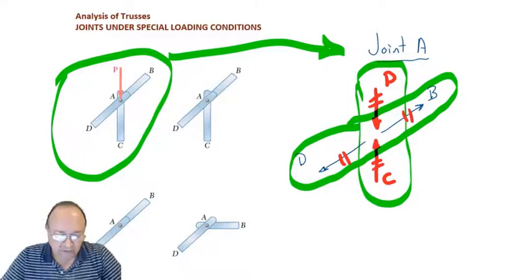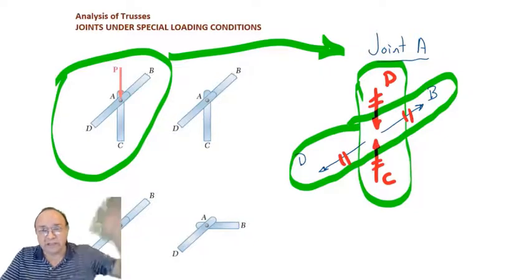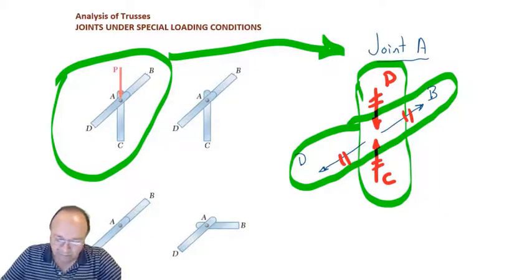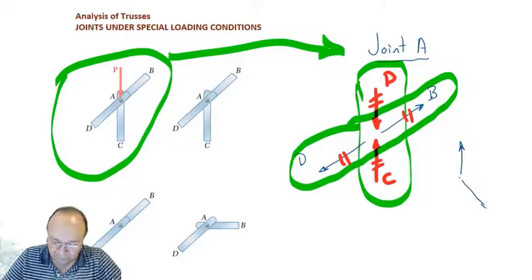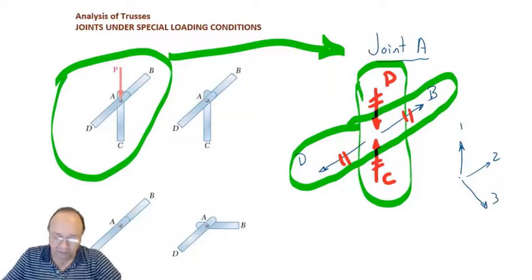This comes from the construction of the polygon of forces that we study at the very beginning of the semester. If you remember, when we have a particle with three forces applied, let's say we have 1, 2, 3, the graphical method to get the resultant of those three forces was to make a drawing of all the forces one after the other.